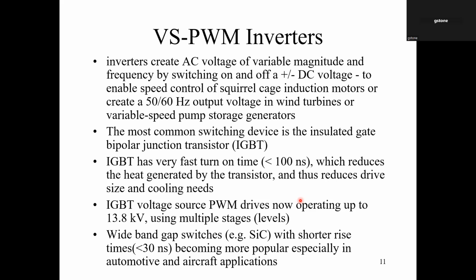so the converter or inverter does not overheat. Okay, and this is why the IGBT and now the wide bandgap switches are becoming more and more popular, because they allow smaller footprints and smaller heat loads for equivalent power output from the inverter.